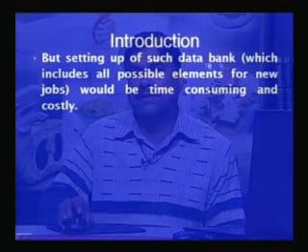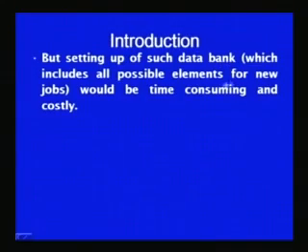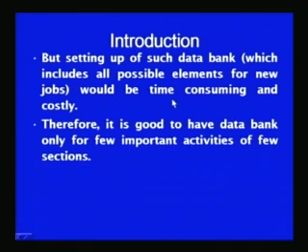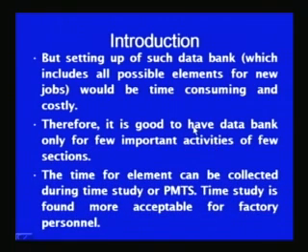But the setting of such a data bank, which includes all possible elements for the new job, would be very time consuming and costly. Therefore, it is good to have the data bank only for a few important activities of the few sections where changes take place very frequently, and the time for elements can be collected during the time study or PMTS method. The time study is found to be more acceptable for the factory personnel.